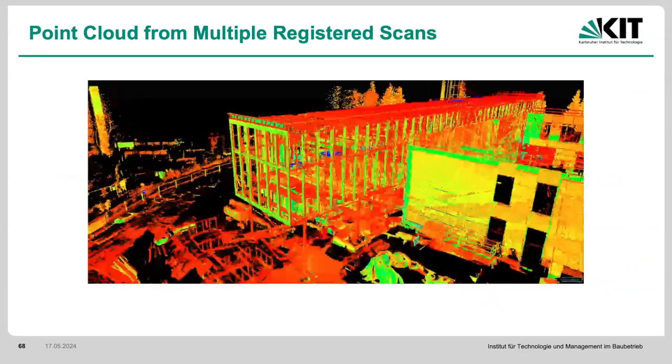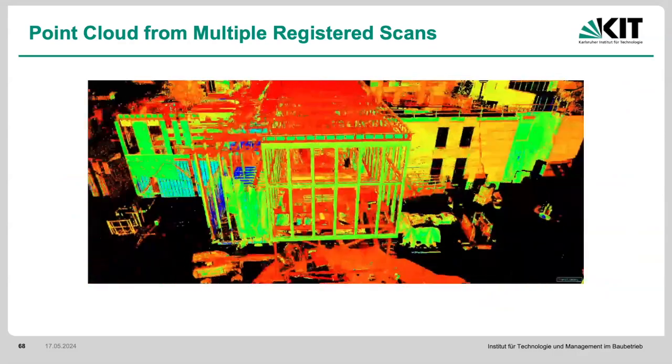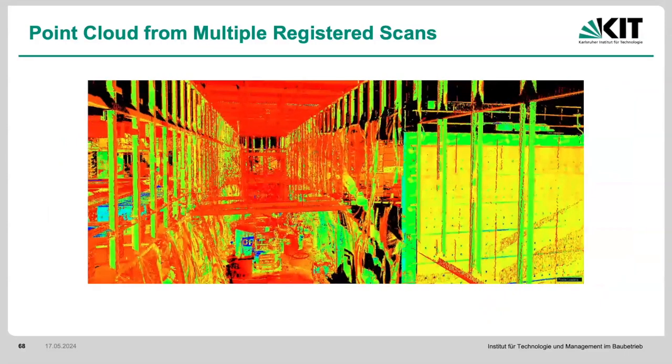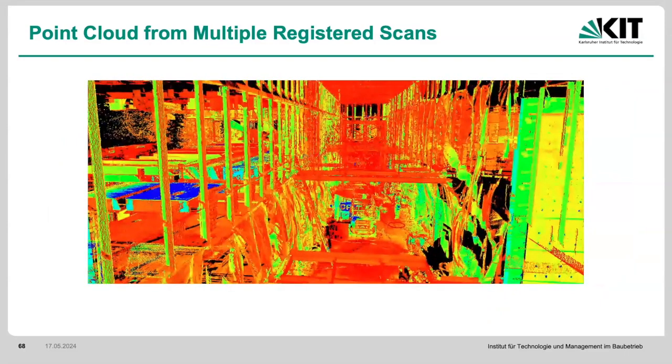Okay. And this is going to be the final result of multiple registered scans. Typically, once you have a general registration between scans, you do an ICP, or iterative closest point registration, to kind of force it together. We will be using iterative closest point registration to register your point clouds of, let's say, a neighborhood of a digital model object. You get all of those points, and then you iteratively match them together, bit by bit, through iterative closest point. That's basically going to be your final project.